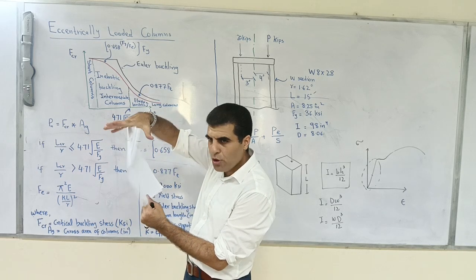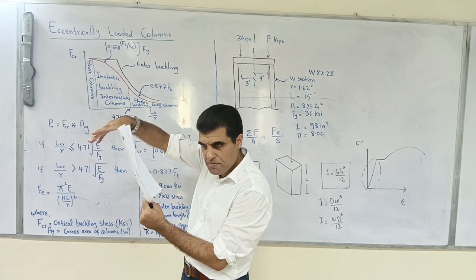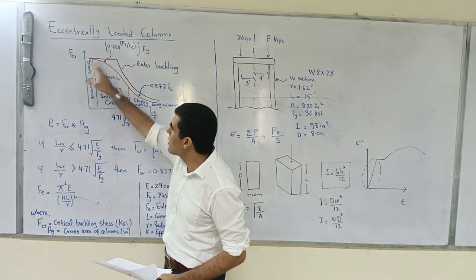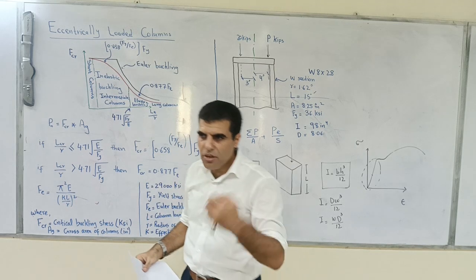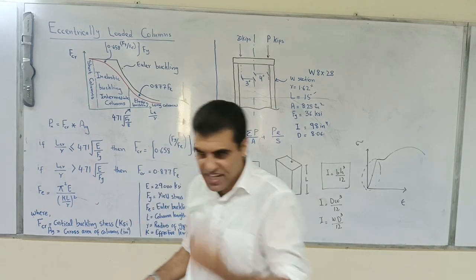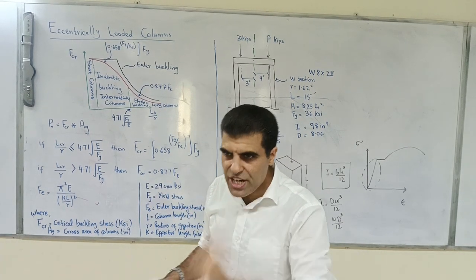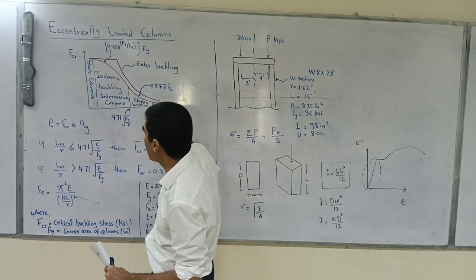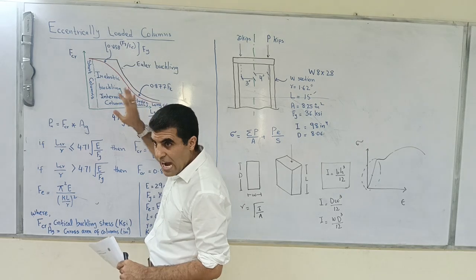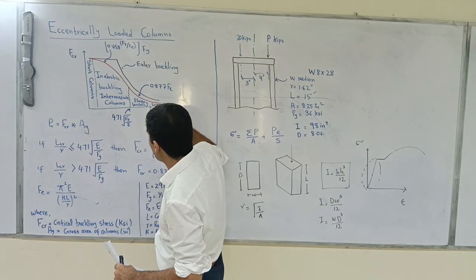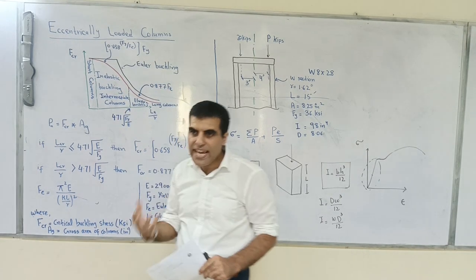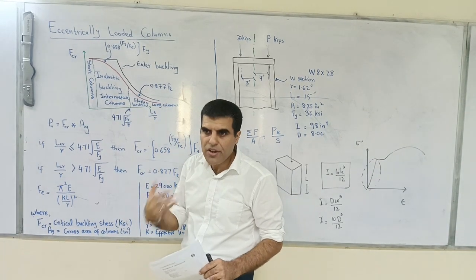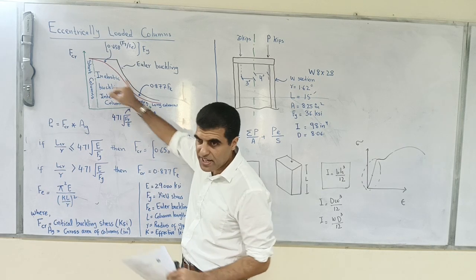Okay, so when you put the load on the slightly inclined compression member, what will happen? You won't follow this curve. Because of these tolerances and the internal stresses, you normally don't follow exactly this curve, but a curve which is slightly lower than the actual curve. So that's why normally the code of practices consider this red curve and give you the equations corresponding to this red curve.